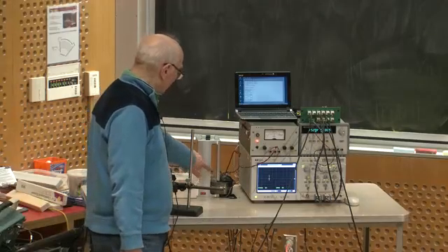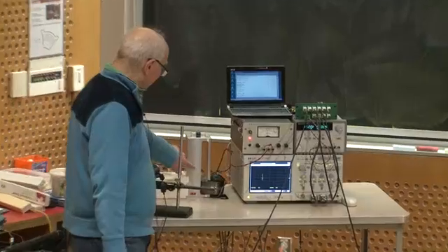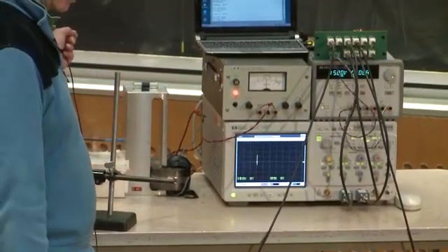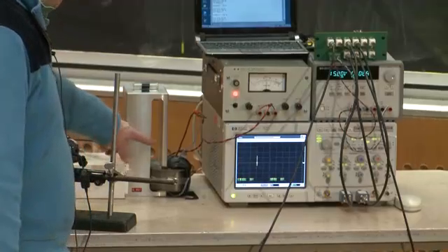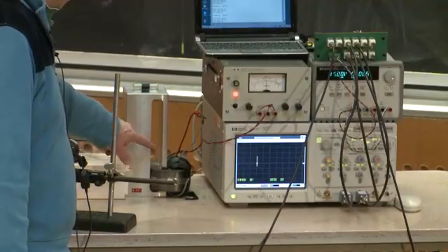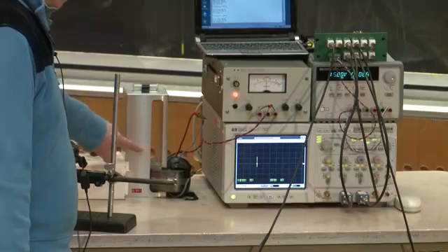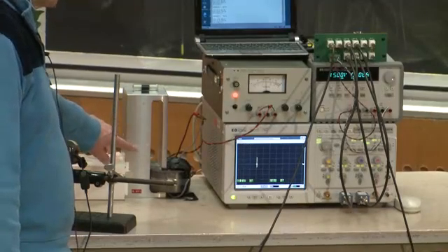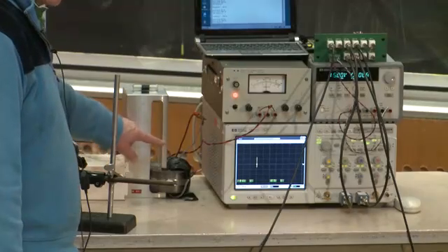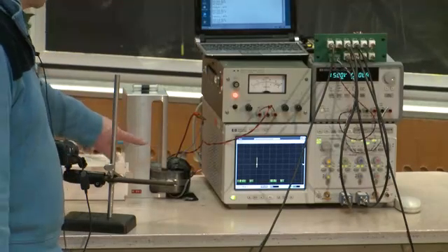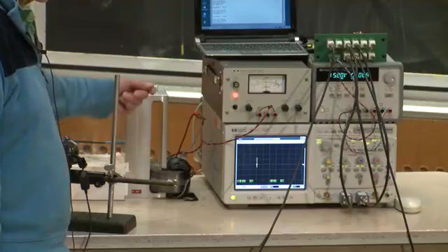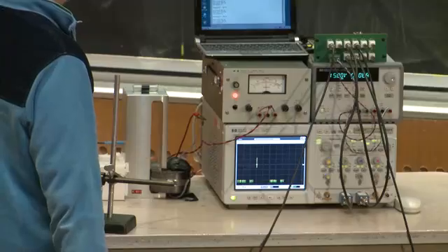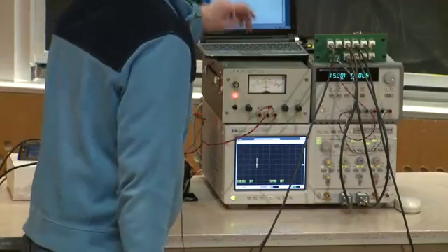Now, when we move it from the edge to the middle, we're going to excite our transformer at 60 hertz. Okay, so relatively low frequency. And so the skin depth will be quite long, and so we should get good current in the block, and we'll see that it goes quite deep into the block. And then when we return, we're going to turn up the frequency to 240 hertz, and then we're going to see how that compares to the 60 hertz result. So the first time, I'm just going to run it so that you can see how the apparatus is working, okay?